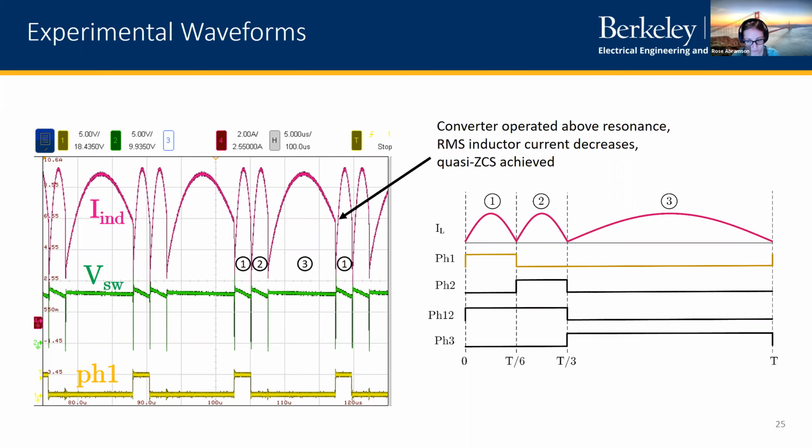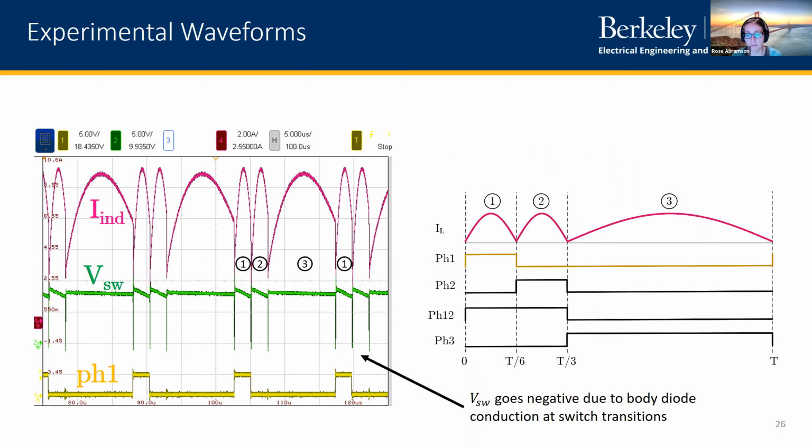For example, capacitors could be 10 or 20% tolerance, and then you would have to match that over the entire converter operation to effectively track the resonant frequency if you were operating exactly at resonance. But now we've removed that, and we don't care what that exact resonance is as long as we're operating above it.